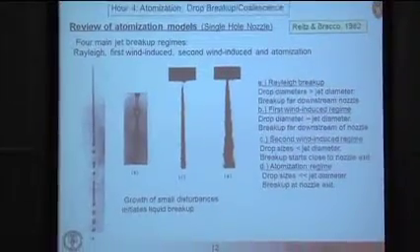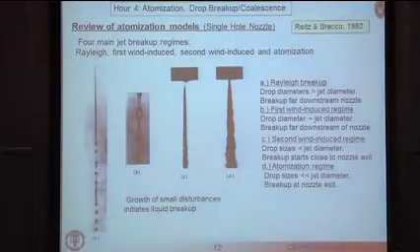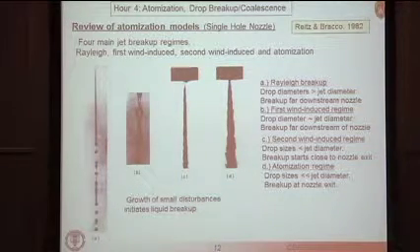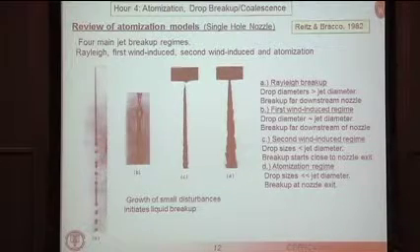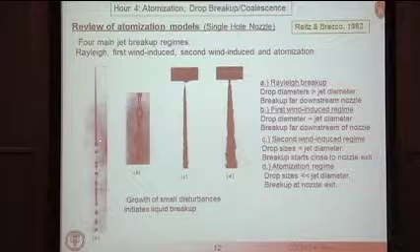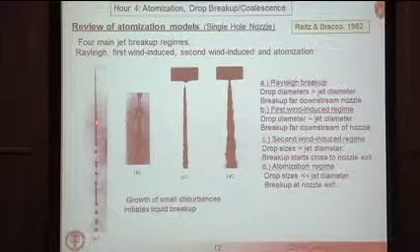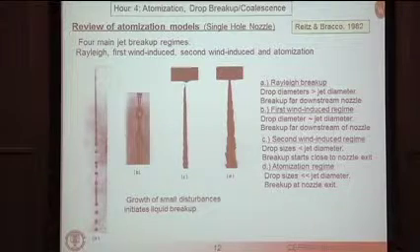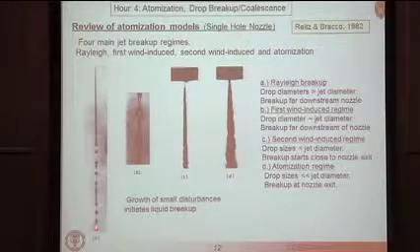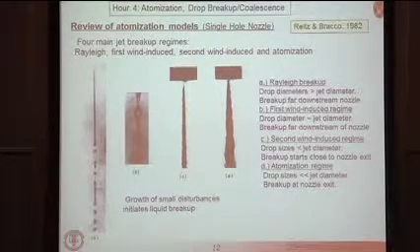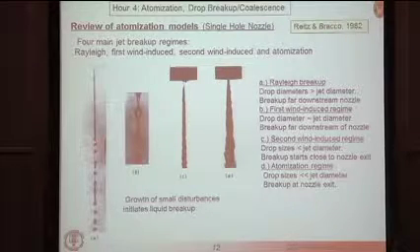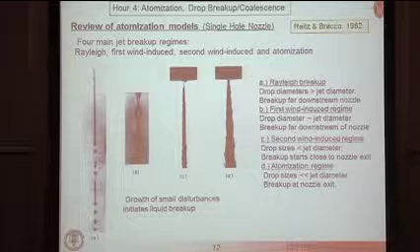Okay, so let's start with just an overview of atomization work. This is actually out of my PhD thesis many years ago, a description of what happens when you inject a liquid through a single hole orifice. If you have a very low velocity jet, what you find is a continuous intact stream of liquid. Surface tension leads to instabilities that grow on this jet, and eventually they pinch off droplets here. So this is due to surface tension. You'd see pretty much the same breakup if you did this in a vacuum or whether you had a low gas density environment. This is referred to as the Rayleigh breakup regime.